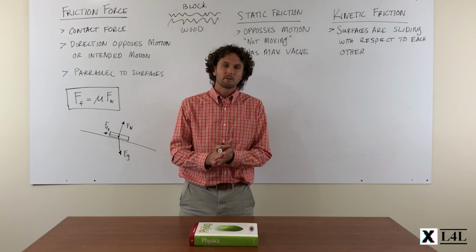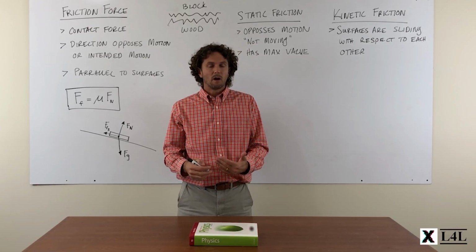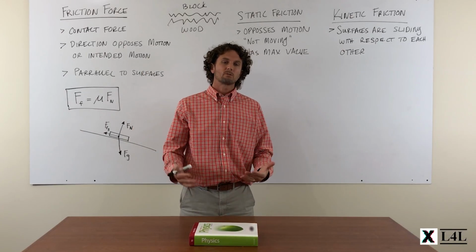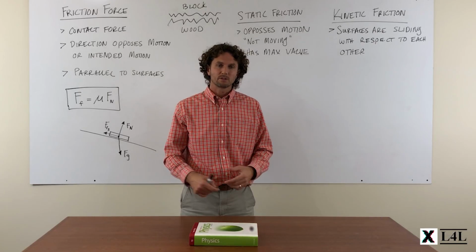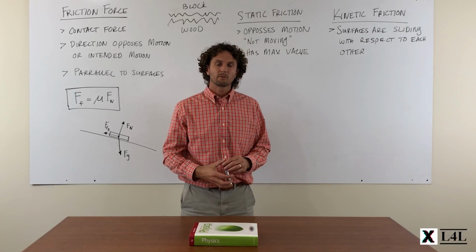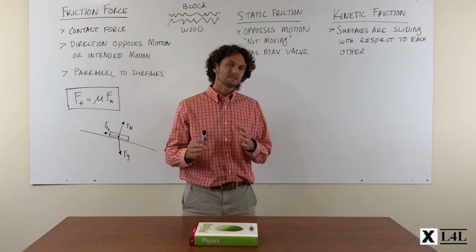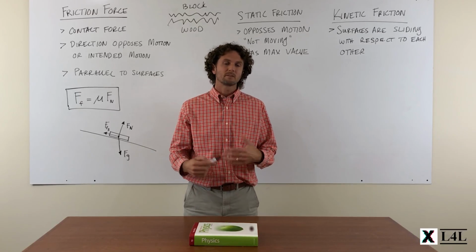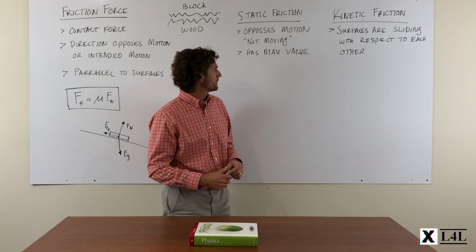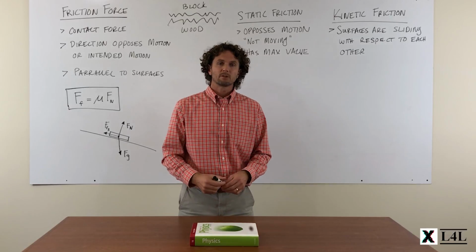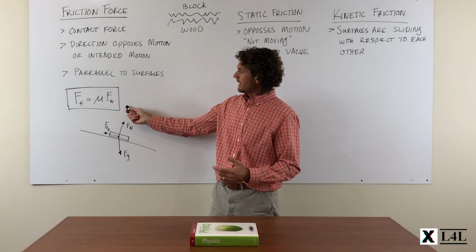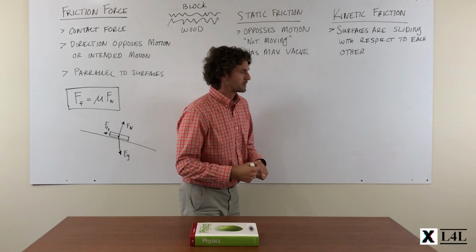All right, as you can see from the chart, clearly there are differences in the types of materials when they're in contact with each other. And what was also obvious from the chart is that the coefficient for static friction was always greater than the coefficient for kinetic friction. This is why, and we'll talk about it in a later lesson, when your tires are in contact with the road, you want to keep your tires in static friction. You don't want your wheels to spin out, because that's when you lose control and grip of the road, especially if it affects your braking power. To drill down further on static friction versus kinetic friction, there are actually two separate equations that we can use to look at this overall equation for the force of friction.